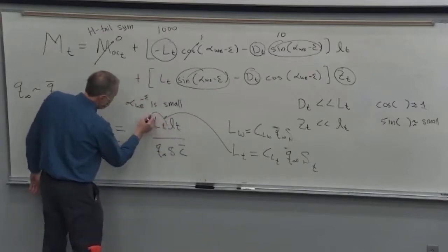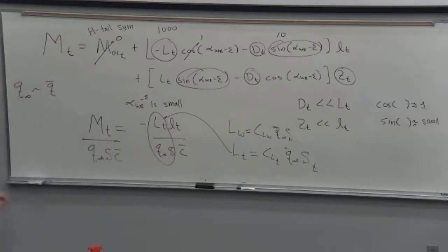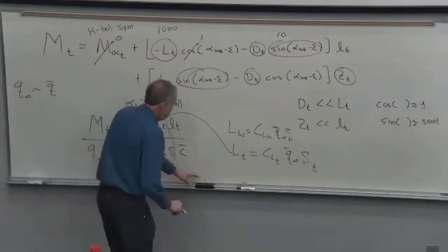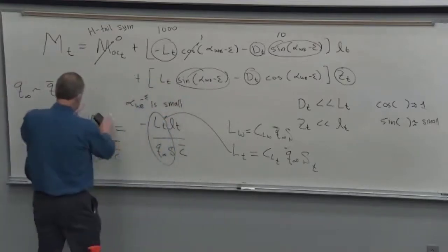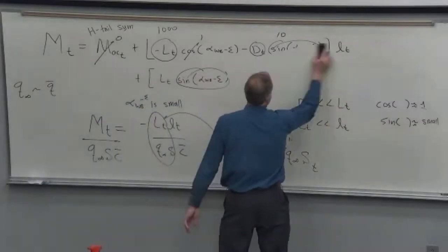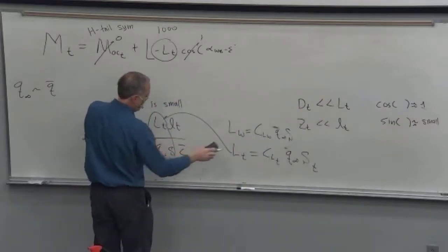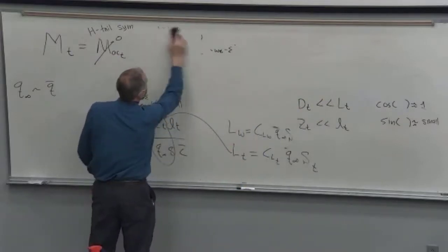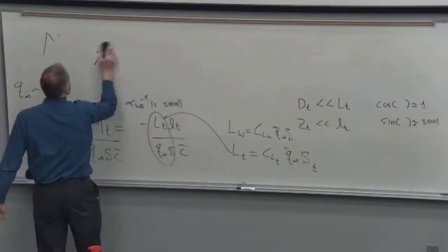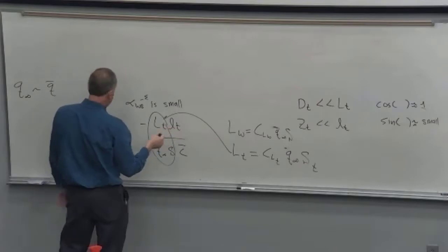It's real tempting to just say, well, this is CL of the tail. And that's not true. CL of the tail is based on its own area. So this is still CM of the tail in terms of the whole airplane. And whenever you have the tail in a formula, we're always going to see this ST over S ratio. The reason for that is just because of how you predict the lift of the tail.